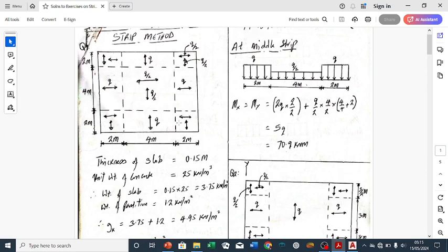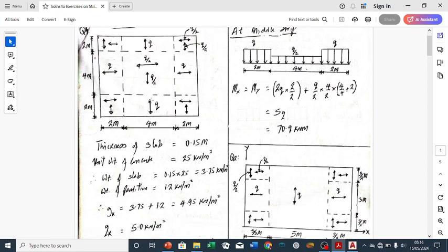But when we come to this space, remember all the load was in the vertical axis and it has a value Q. The same thing here. When we get to this point, all the load was in the horizontal, value Q. There was nothing in the vertical. The same thing also happens here. But in this middle portion of the middle strip, the load is distributed equally: Q/2 in the horizontal direction, Q/2 in the vertical direction. So having done that, we have been able to distribute the load.